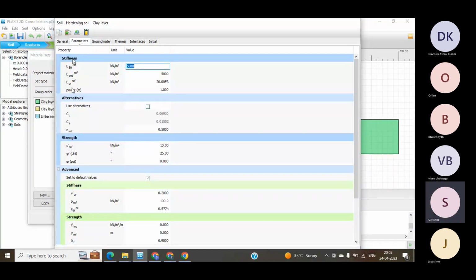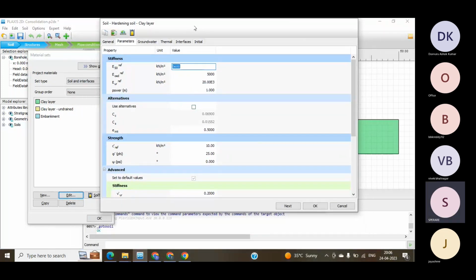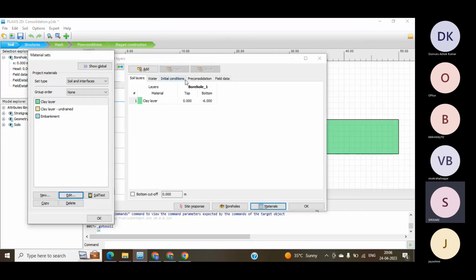It means that they can be called multiple times, like you are excavating something and after that you find that particular soil, which you can treat as a hardening soil, or at the starting itself you can consider that as a hardening soil by assuming that, and then start working on it. This is all up to the level of what you are doing in the realistic world. That's all your choice. So you have to understand that and then project it further here. By default, at the starting level itself, I'm assuming this as a hardening soil. There might be some activities performed in the past that I'm not sure of. Maybe by considering those past activities, I'm considering this as a hardening soil also.